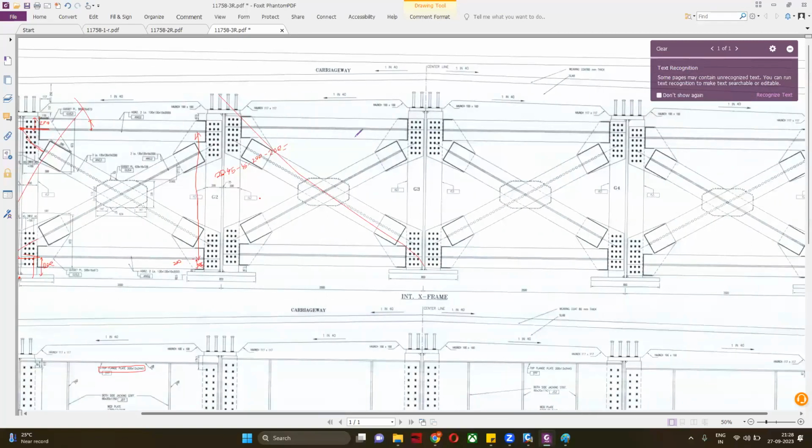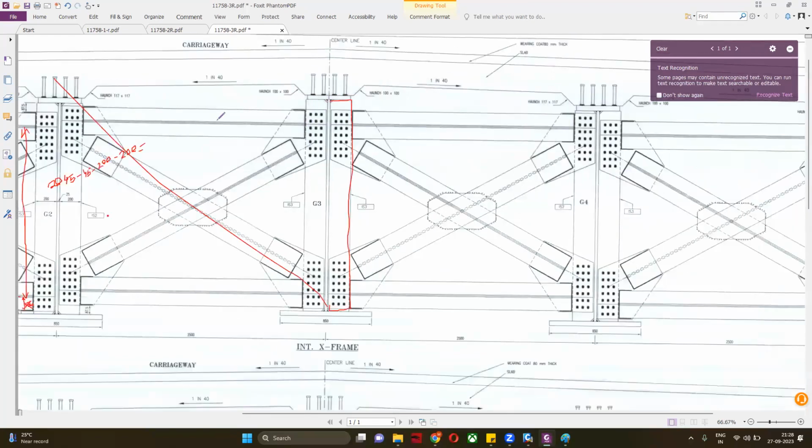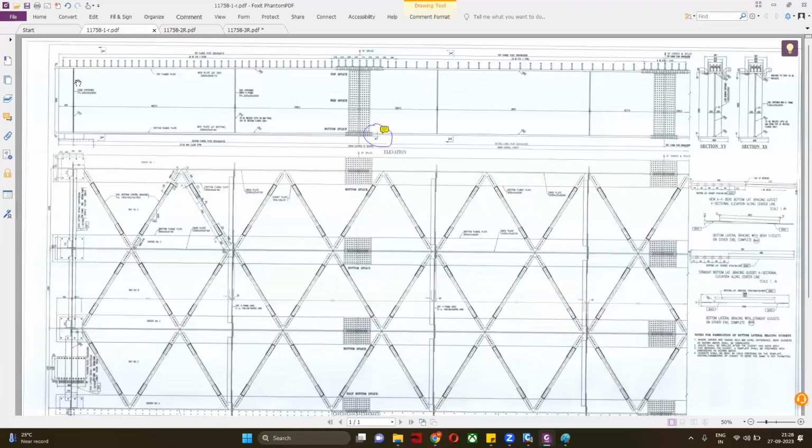So here a stiffener is also there. This is totally a stiffener, because your connection is only possible through a stiffener. Our stiffener will resist our web, providing strength. Is it only one stiffener, sir? This is one stiffener. Two stiffeners are generally required at a bearing location, but in this case a bearing location is not required, so only one is provided.